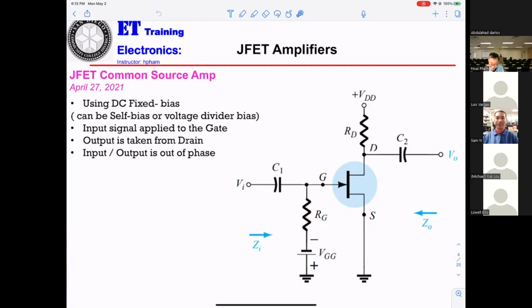So the voltage between VGG and the gate will be the same. If you don't want RG here, you can short it here. Take it out, short it. It's still working for the DC offset. Usually the DC bias resistor is in the mega ohms, really high, right? Yeah, at least 1 mega.